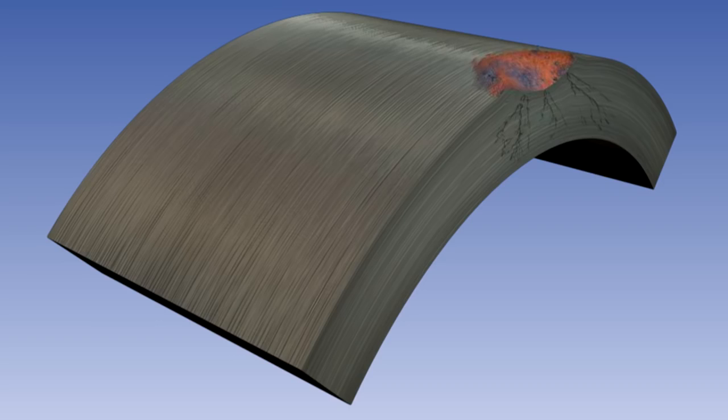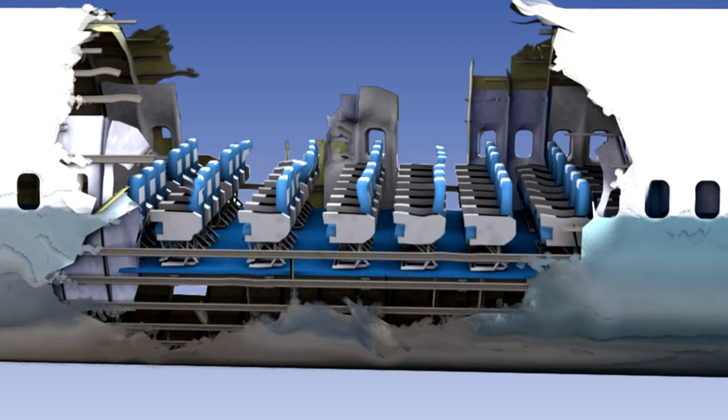A combination of a steady tensile load and corrosive environmental conditions produce a form of metal fatigue known as stress corrosion cracking. The stresses may be built in during manufacture, introduced during assembly, or may be applied during operation. Metal under stress corrodes more rapidly than unstressed metal. It usually begins with pitting at the surface. This increases the stress at the pit, causing a crack which can extend under the combined action of corrosion and load until failure occurs. There is generally very little evidence of corrosion and no apparent loss of metal. This type of corrosion is often not spotted until a serious failure occurs.